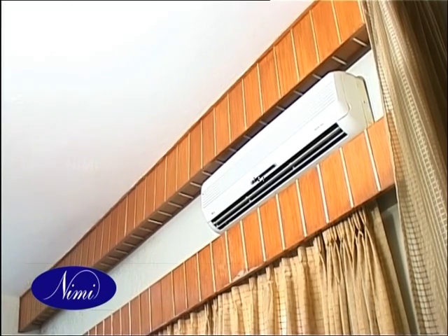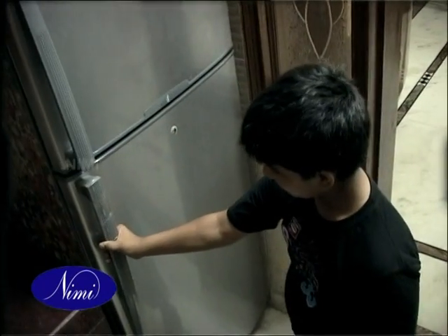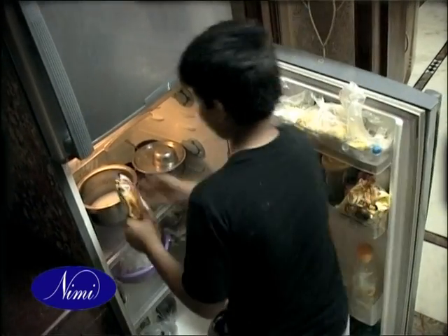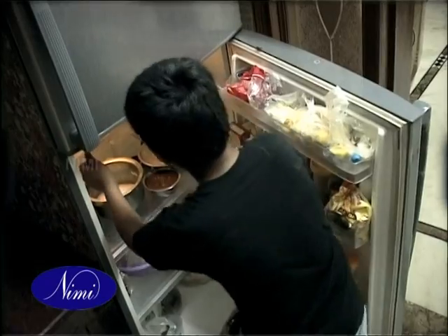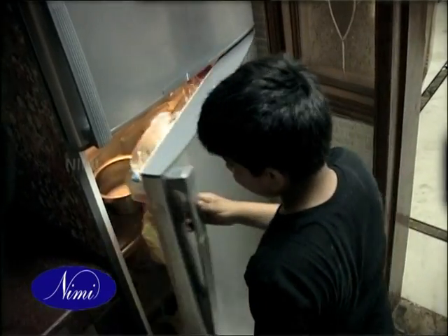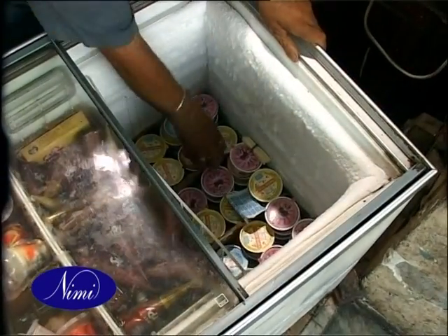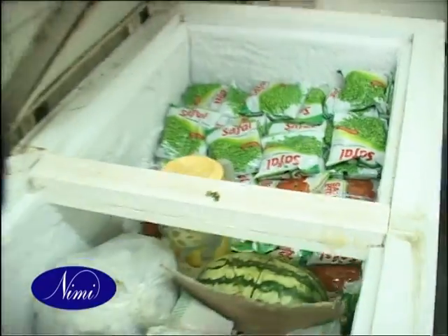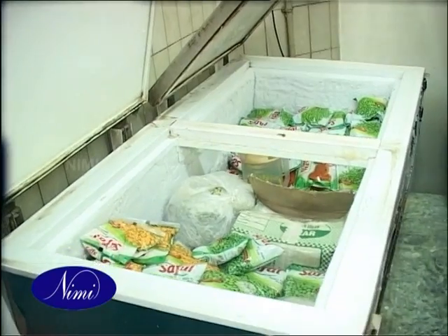The high temperature refrigeration systems are used for air conditioning equipment where temperatures between 25 to 45 degrees Fahrenheit are needed. Medium temperature systems are used for food storage and other applications requiring temperatures between 25 and 0 degrees Fahrenheit. Low temperature systems are for those applications requiring temperatures of 0 degrees Fahrenheit or below.